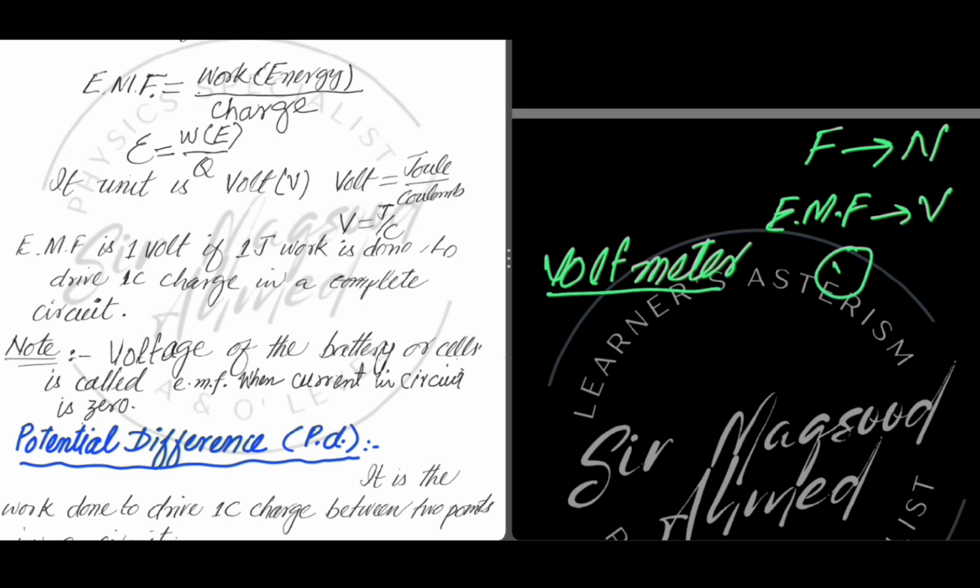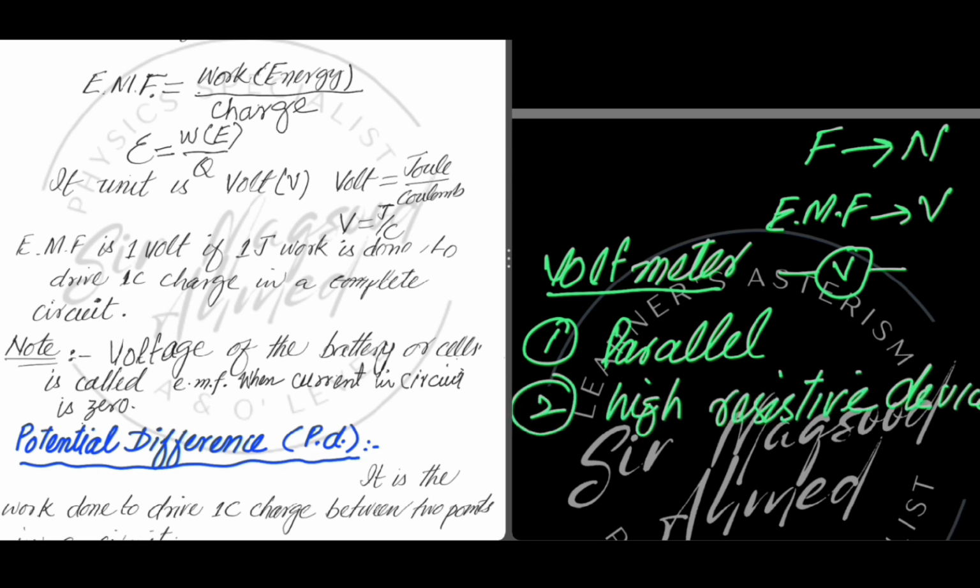Its symbol is as shown. Now regarding the voltmeter, you must keep in mind two things. Number one, the voltmeter is always connected in parallel. Number two, the voltmeter has very high resistance.